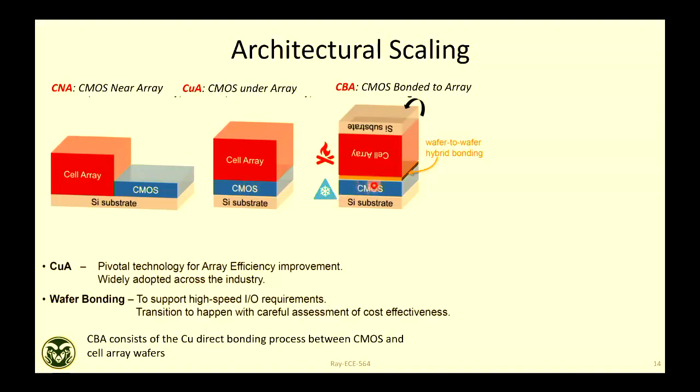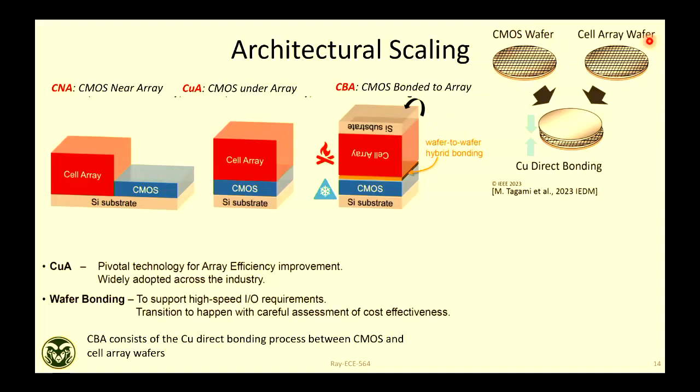So that's why the industry came up with this hybrid bonding technique, where you have 2 substrates. You grow your CMOS separately, with a different process, totally decoupled. After you make both, memory array on one substrate and CMOS on another, you bond them together. There is a lot of advancement in wafer bonding techniques, like advanced packaging. So this is what they do. They take 2 wafers. Your cost is pretty much double, and that's why industry delayed this technique.